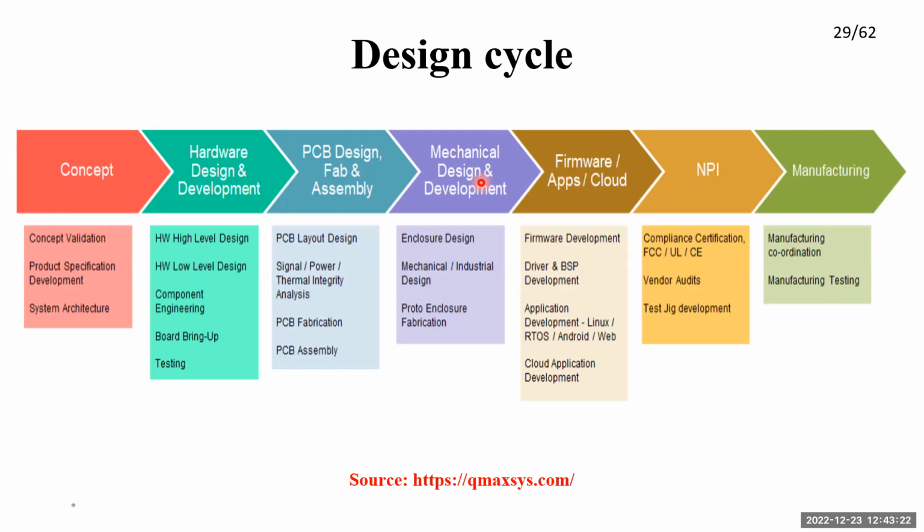Next is the NPI, which means new product certification. For example, once you are done with everything, you are done with the software, you have integrated it and your system is working fine, then you go for compliance testing, or various kinds of testing. Once all are completed, your prototype is completely ready. Then you go for manufacturing, basically. Manufacturing, then production testing, we used to call it.